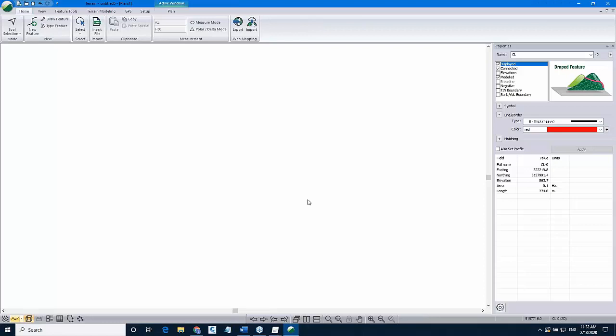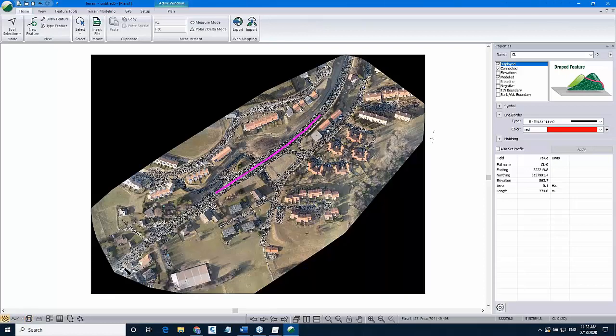This is another option that we have in the terrain model: we could import different layers, create a surface for these points, and start drawing a feature or an alignment for the road. Then I can use the location model, export this terrain file and also the existing feature center line, and use the location model to continue designing the road.